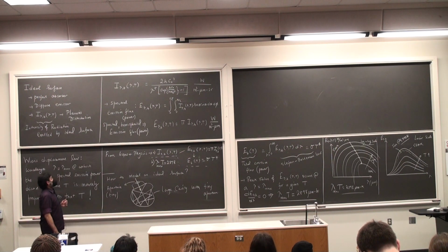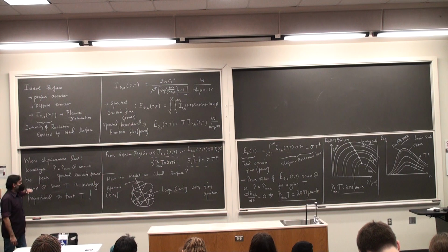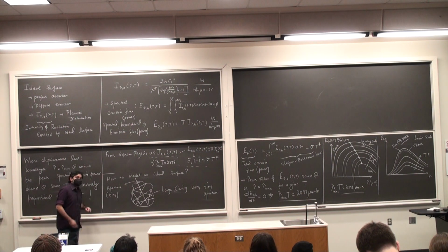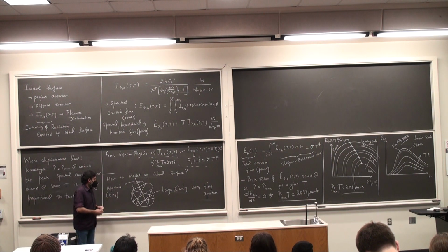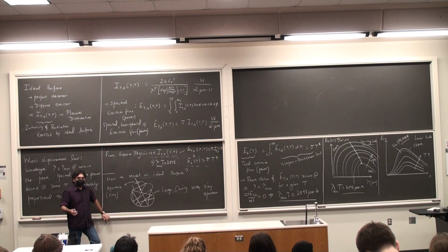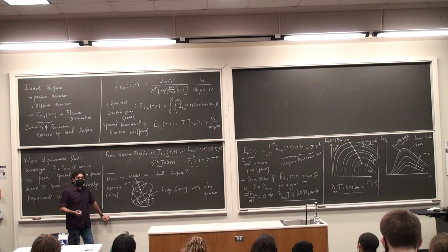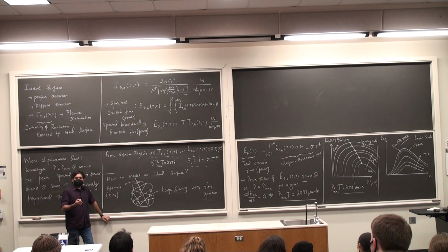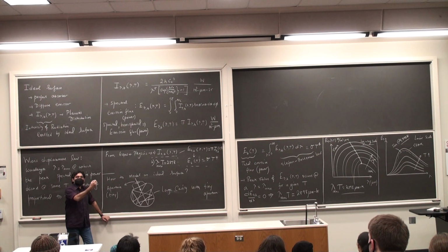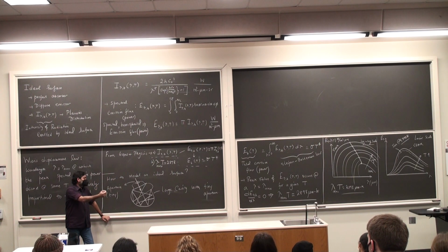And to satisfy the second property, which is the diffuse emitter, here is what happens. Every ray of radiant energy can be thought of as a packet of photons, a packet of energy. Okay? So these packets of energy come and strike the inner surface of this cavity. They carom off of the surface.